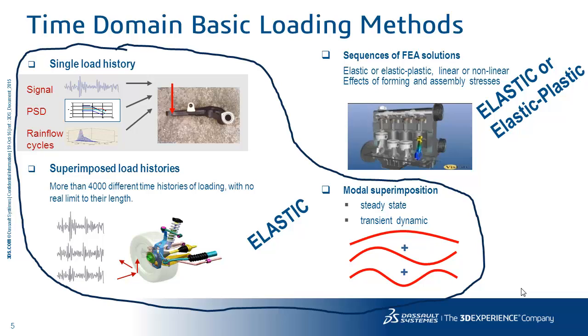So if you imagine the rocker arm and the engine rotating, say, through two full rotations, and you have a transient solve every 5 degrees for 720 degrees, you can bring that sequence of stresses and strains into FE-Safe, and FE-Safe will create a duty cycle at every node for that model.